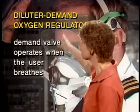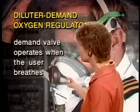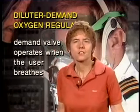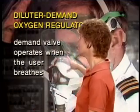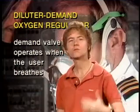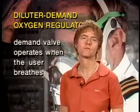In the diluter demand oxygen regulator system, whenever the user breathes, the demand valve operates. In the other system, the continuous flow, the oxygen does just what its name says. It flows all the time. In the diluter demand system, you only get oxygen when the user breathes, and that is much more conservative in the use of oxygen because you don't have it flowing out into the atmosphere when the person isn't breathing and isn't using it.